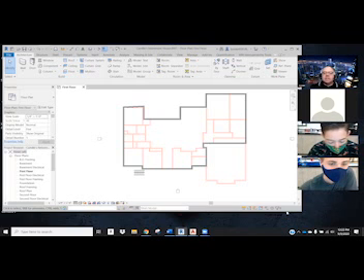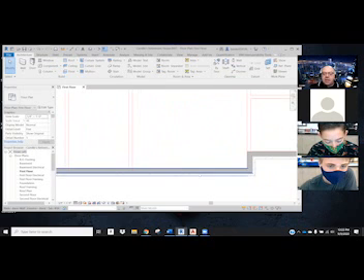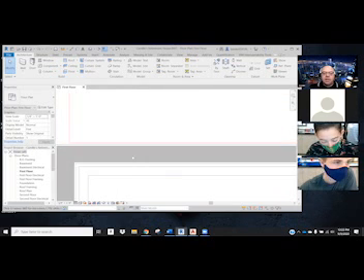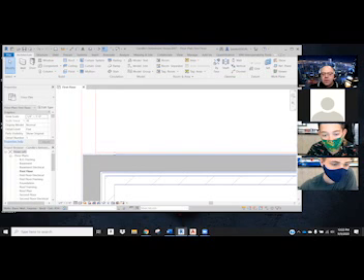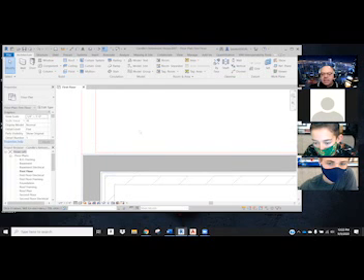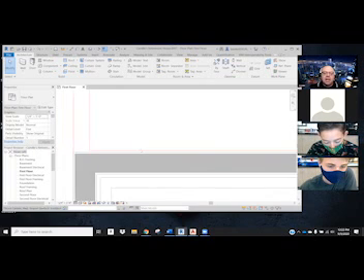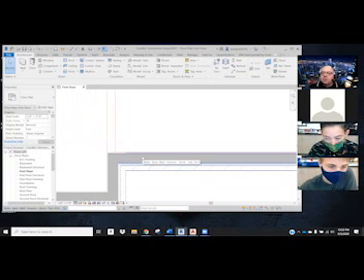Okay, let's talk about these errors that I threw in here. The first one actually happened down here, clear over here. And so I'll keep zooming in here. You'll notice there's a red line that's inside of where my walls are. My walls aren't lined up here. So you see this little line there, and then there's my wall. I want them to be what my plan was when I did them in AutoCAD.